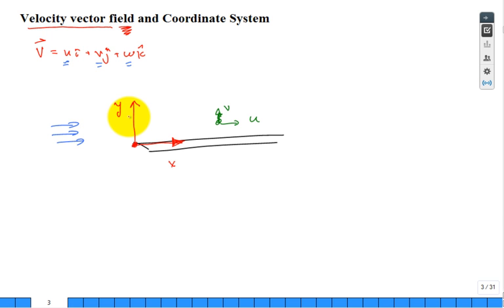But it's going to be a little bit problematic or challenging for you to remember these things if you remember from fluid mechanics, because you'll say, come down to this location X right here. Just pick that. That's the distance from the leading edge. That's X. Okay. I want you to sketch the velocity profile. And so what you'd do is you'd say, well, it's going to come out like this. And way out here, it's all just U infinity. The presence of that knife-edge flat plate hasn't been felt deep into the fluid. So it's all just uniform velocity, just like it was uniform velocity when it was approaching the flat plate.